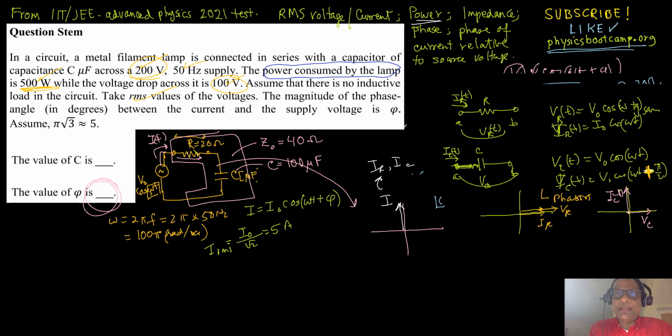Okay, these diagrams say that the resistor voltage will be in that direction. So you have a voltage drop across the resistor this way, and the voltage across the capacitor will be that way. And that should be equal to how much current you have. If you look at the amplitude part only, I have a current, and instead of resistance, you're going to use impedance for the capacitor. So this is the length of this arrow.